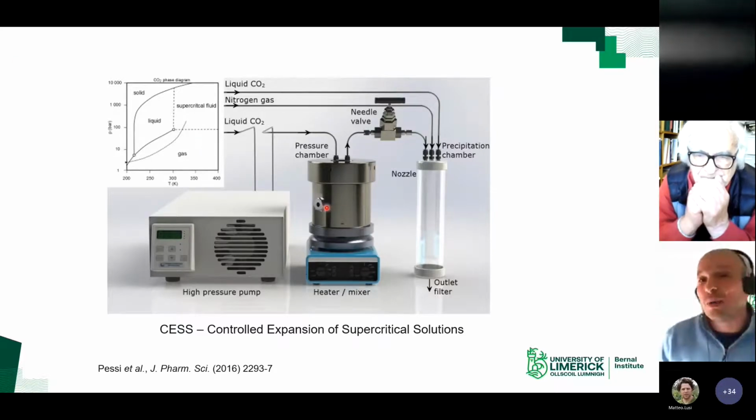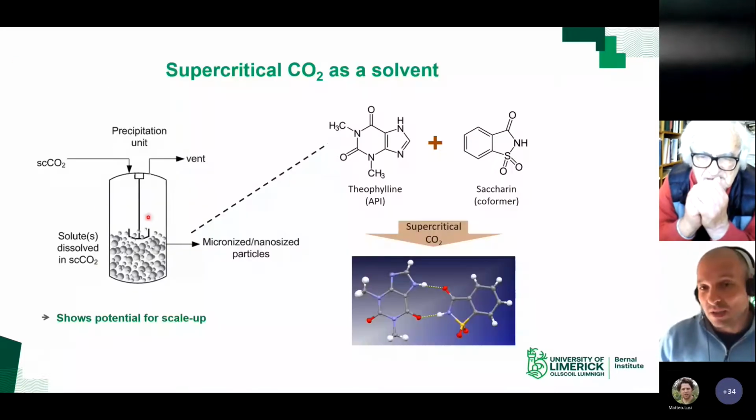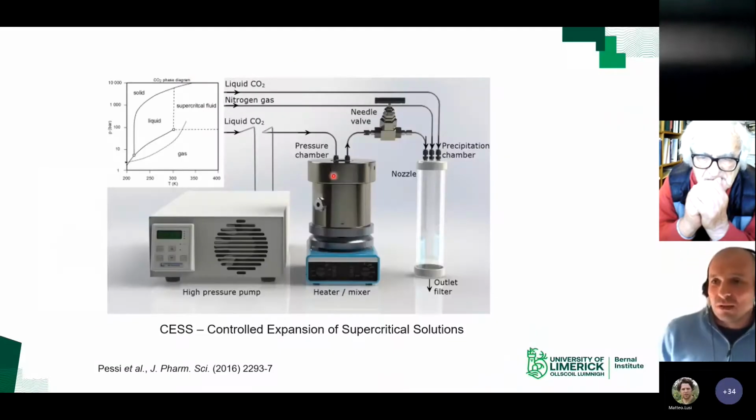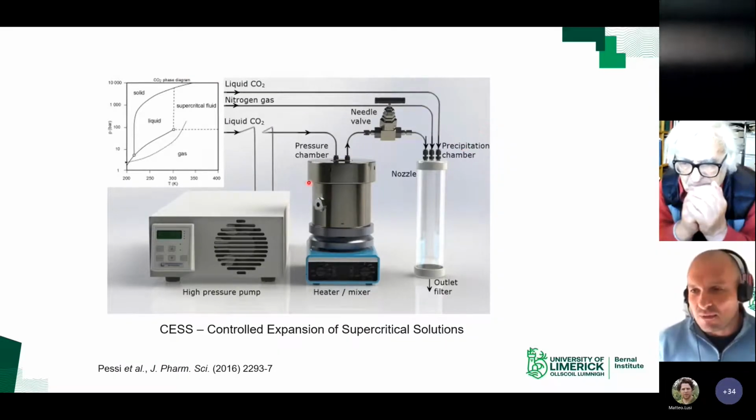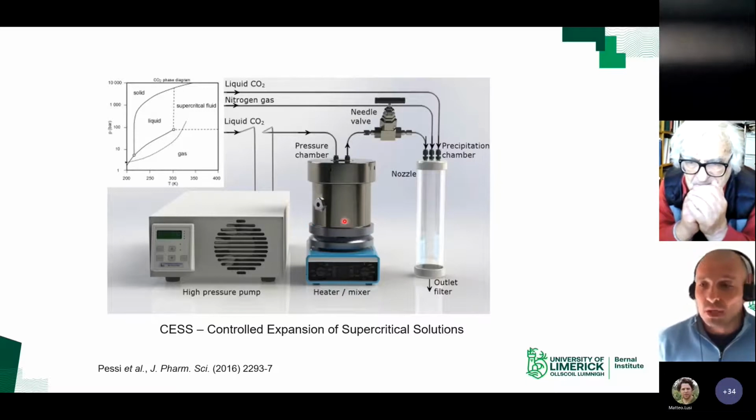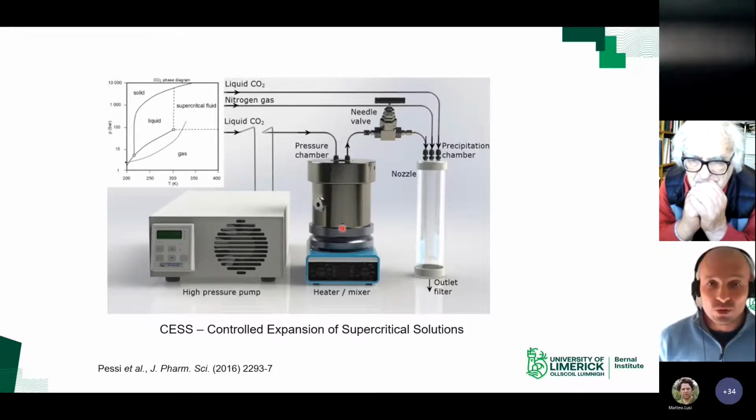But here they do it in a different way to what I was describing here. Here, everything happens in a high pressure vessel. And the way they are doing it, they have taken a conventional method from supercritical CO2 and converted it into something better. In this case, what they have here is a high pressure chamber. So they take a pharmaceutical drug, which is typically poorly soluble in water. They put it in the high pressure vessel, and the CO2 will fully dissolve it.